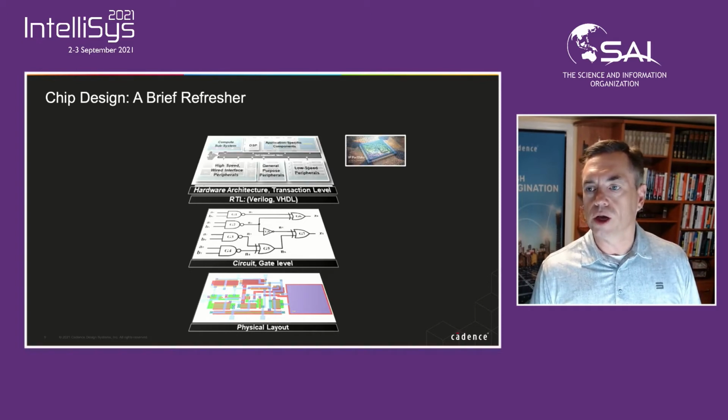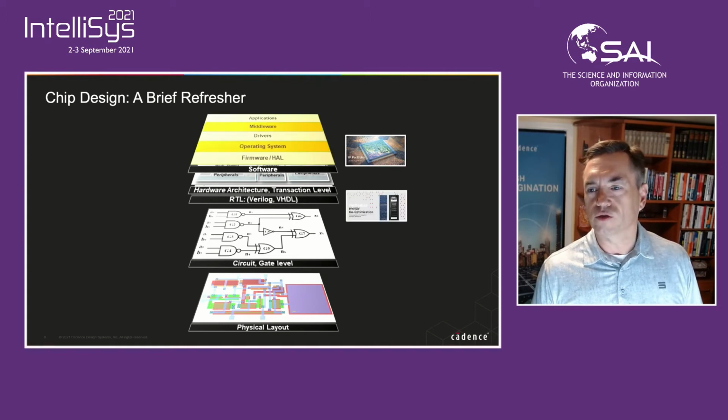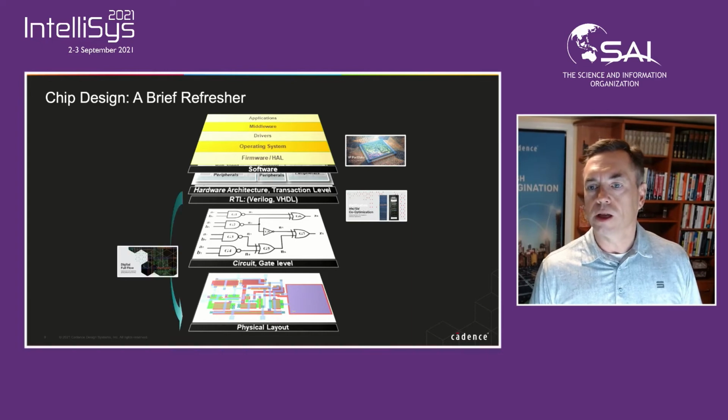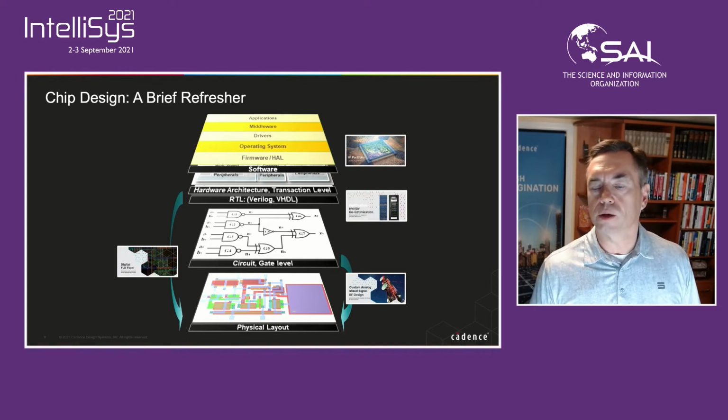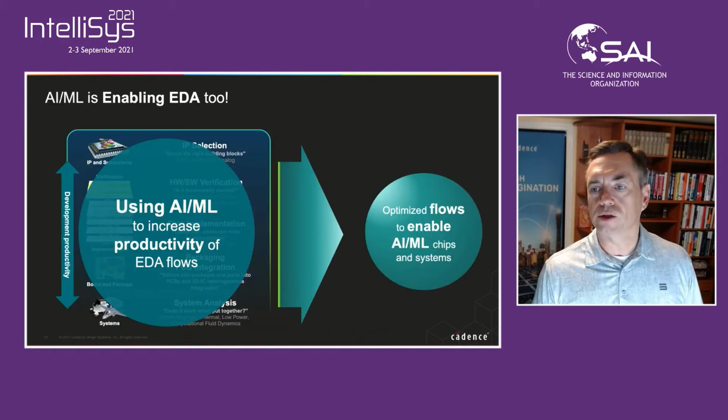a silicon technology. There's IP reuse going on, with a lot of software having to be put together with the hardware. And then you have flows for digital implementation and custom analog implementation, going from schematics to the layout, and from the higher level description using synthesis to layout, and then from there into manufacturing.